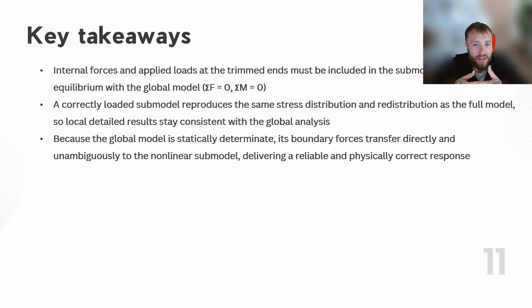So it needs to be balanced, and when the equilibrium exists, you will get consistent results. Because the global model is statically determinate and its boundary forces transfer directly and unambiguously to the nonlinear submodel, delivering a reliable and physically correct model. It works for statically determinate structures.